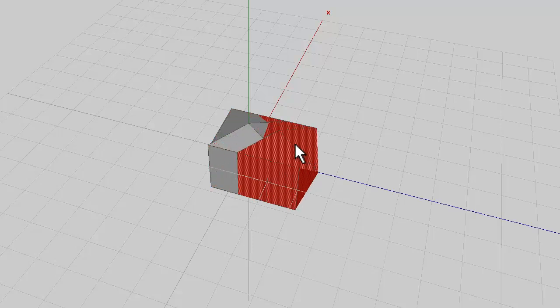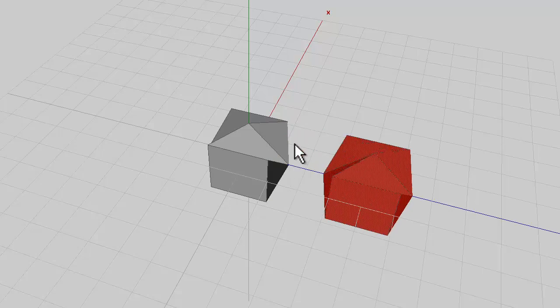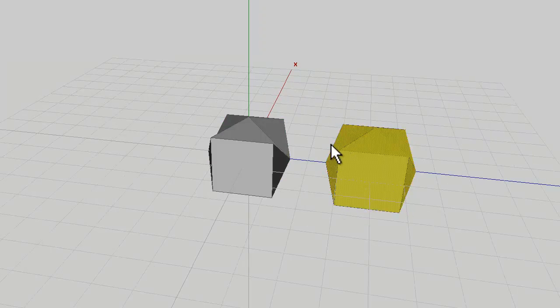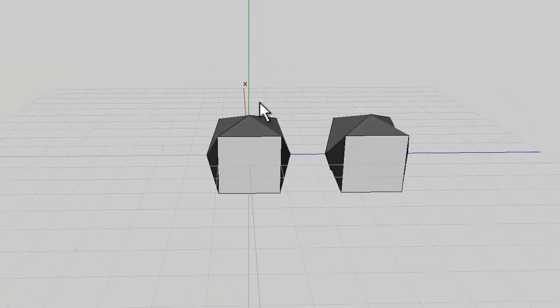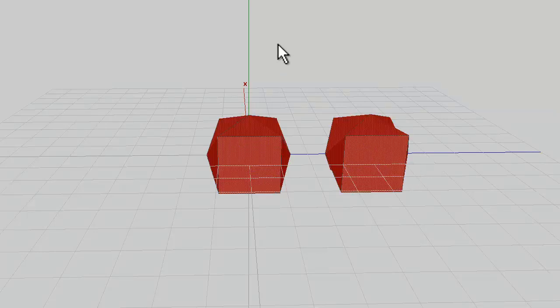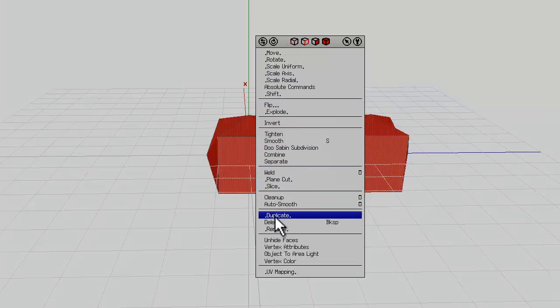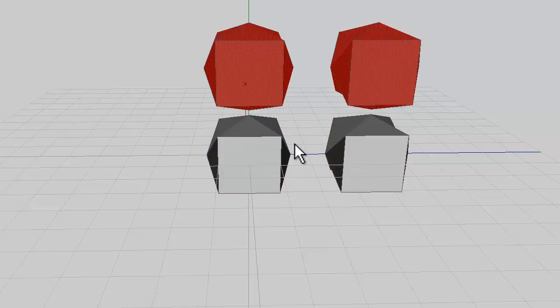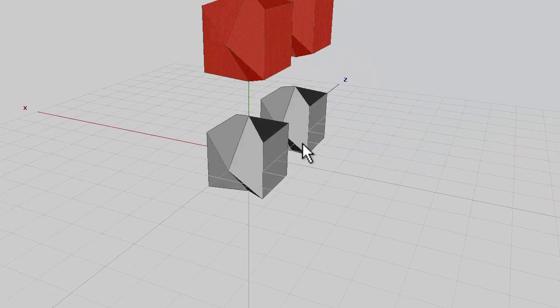So, you need to hold the shift key down and you need to move it so that it'll fit into the gap between itself. So whatever that is, imagine there's a cube face in there, and then you need to select both of them. So select entire object, and duplicate that vertically. So that's along the y-axis in this case. So there's the gap, and there is where they want to be.